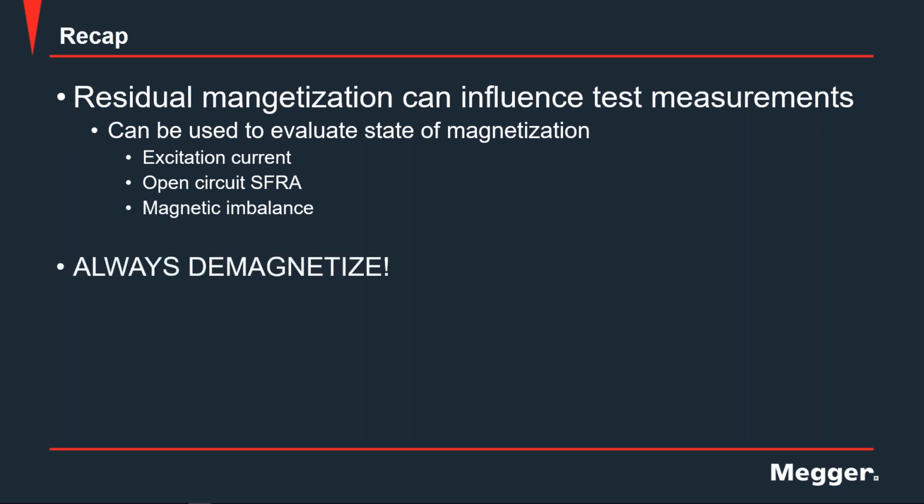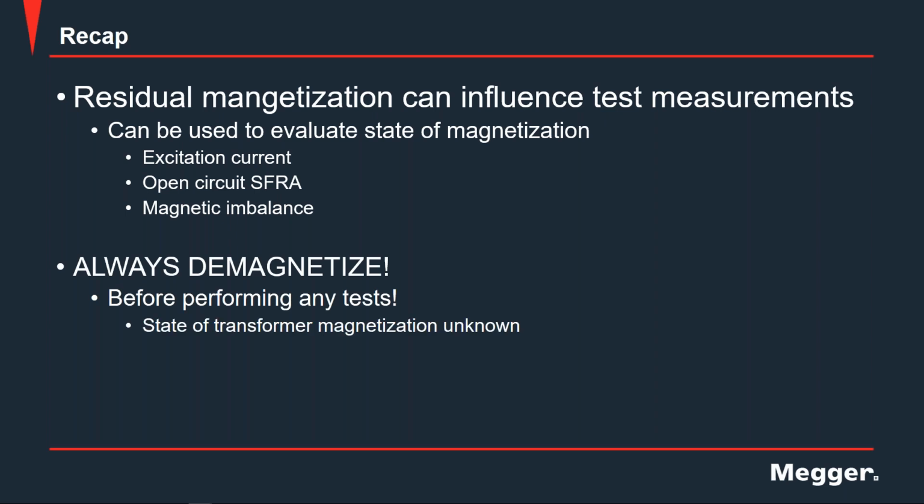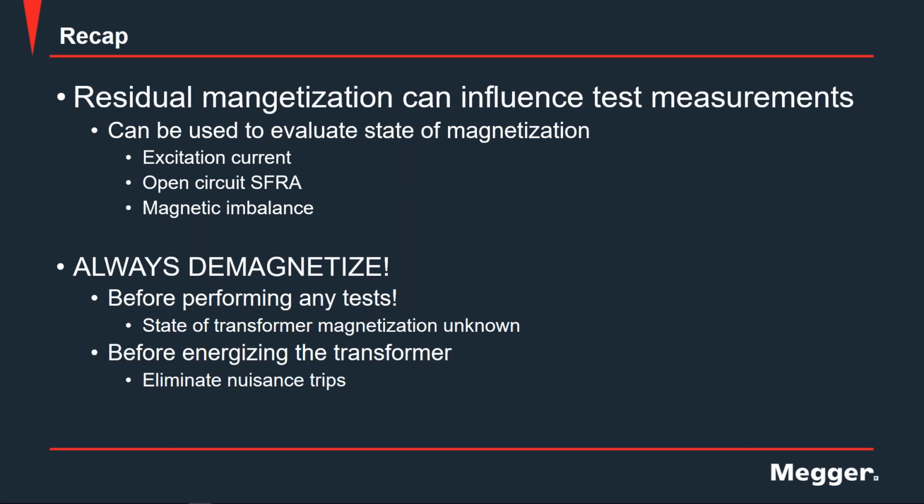The main takeaway is to always demagnetize. Demagnetize before performing any test. Again, the state of the transformer magnetization is going to be unknown, and it's better to be safe than sorry, so just always demagnetize your transformer before you start performing any tests. And always demagnetize before energizing the transformer. You want to eliminate those nuisance trips and provide confidence in your assets.